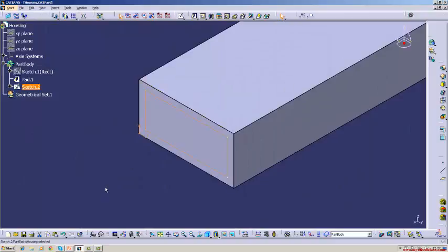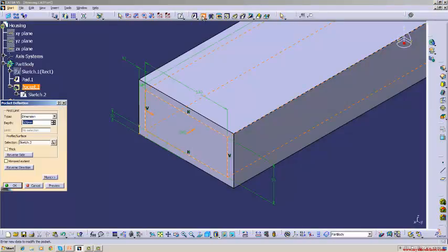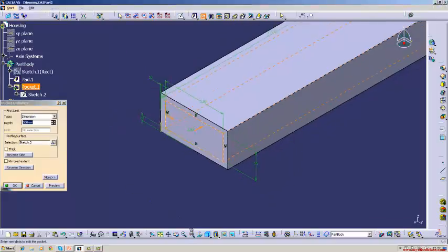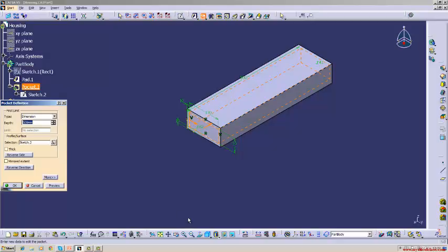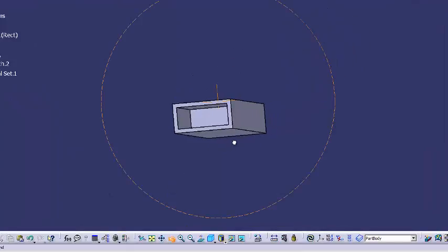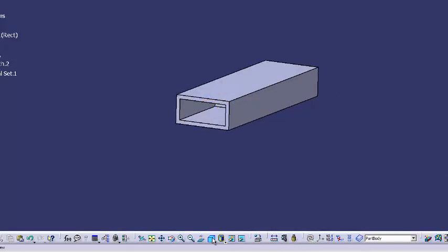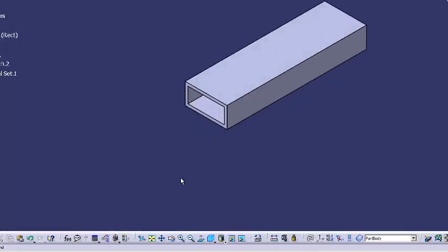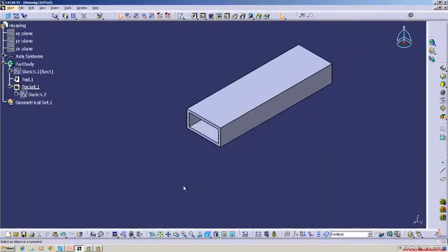Now we have given it. Just drawing a sketch, that's nothing else. Yes. Now only the things should be defined. Earlier we used the pad command, now we are using the pocket command. Pocket command is making hollow, like this. Here you want 500, full 500, you don't want pocket because you could have done it in the pad command itself. So what we can do is, suppose I want to go to 200 and the hole is only up to 200. See. So this is how we can use pocket. So the hole is up to 200.